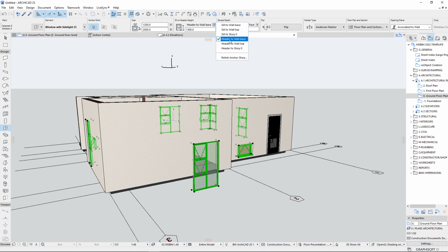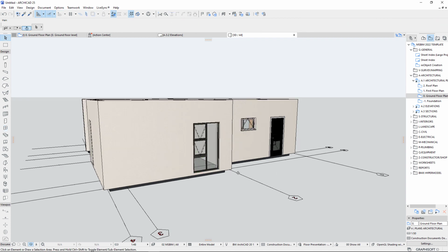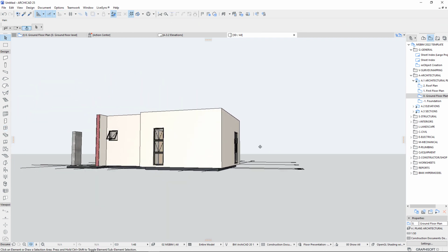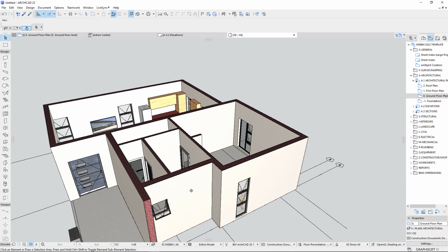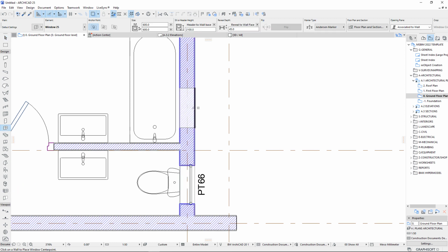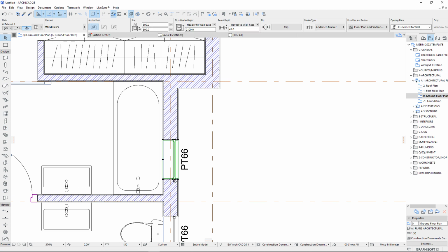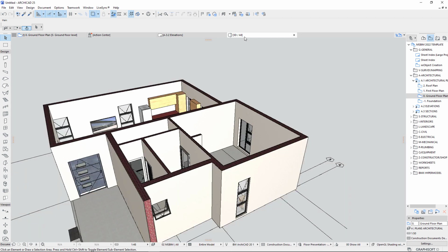This should be what, 2.1. Hit enter. All your doors and windows should be at this level. Nice. We hit another one there. Go back. Yeah, these are some of the strange things that happen when you do your modeling. Things can decide to disappear. There are a lot of ghosts in these things. Perfect. I think everything is fine in terms of all openings.